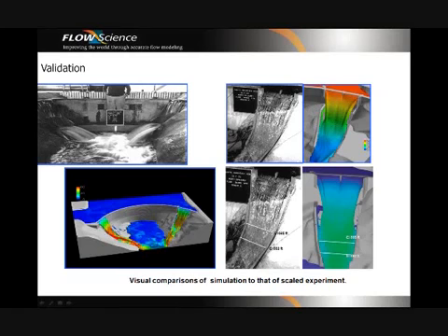The idea was to quickly get steady state conditions by simulating the low resolution version, then starting with the medium version and finally the high resolution version. With each case, the appropriate boundary conditions, initial fluid state and fluid properties were also defined.